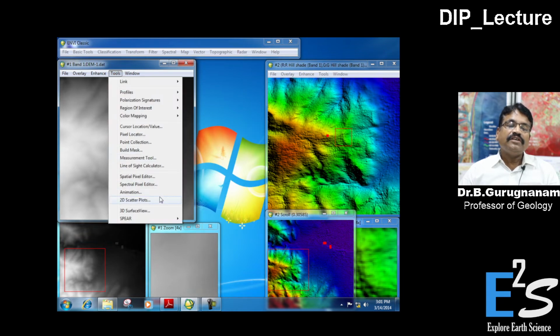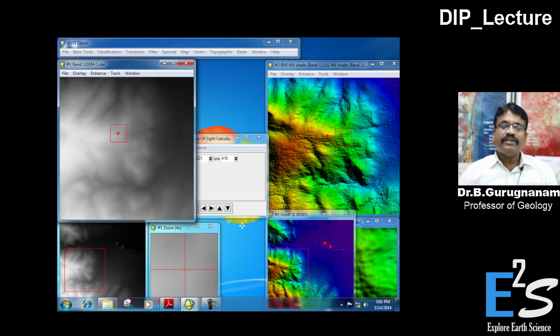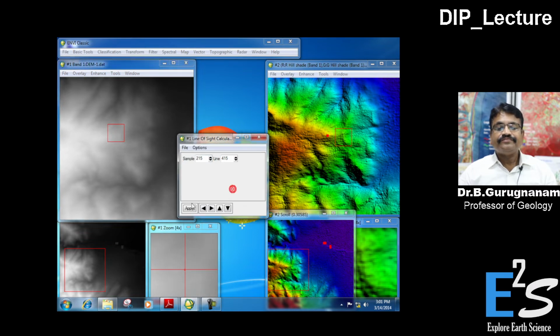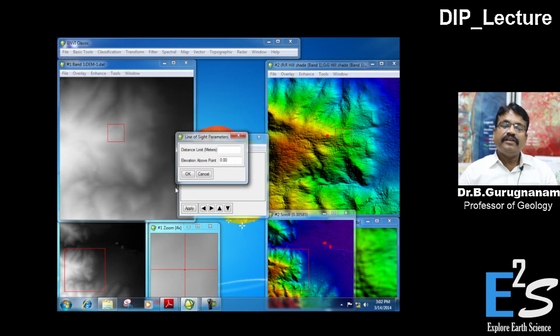Go to tools and line of sight calculator. You take the line of sight calculator and you select the point in the DEM, apply, take the band details and give OK. Elevation above point is 1 meter. The distance at which I want to see at maximum is 3000 meters, I mean 3 kilometers from the point of my visibility.